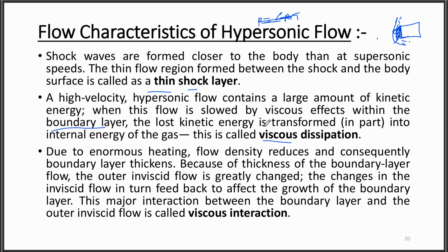This lost energy is transformed into the internal energy of the gas, which is called viscous dissipation. Due to this enormous heating, the temperature will increase, so density will reduce inside the boundary layer.